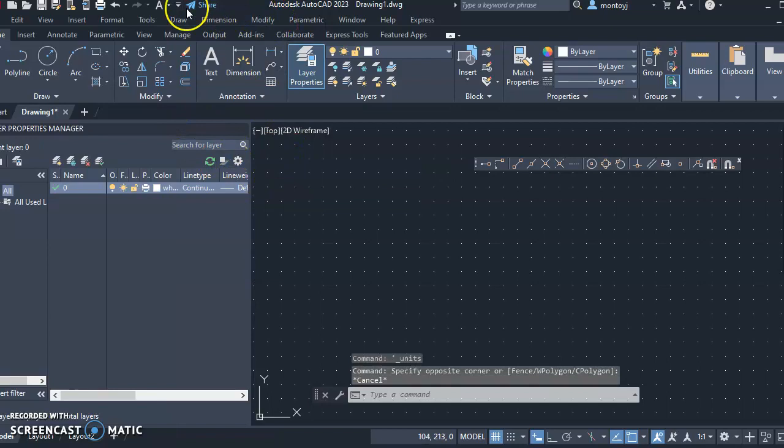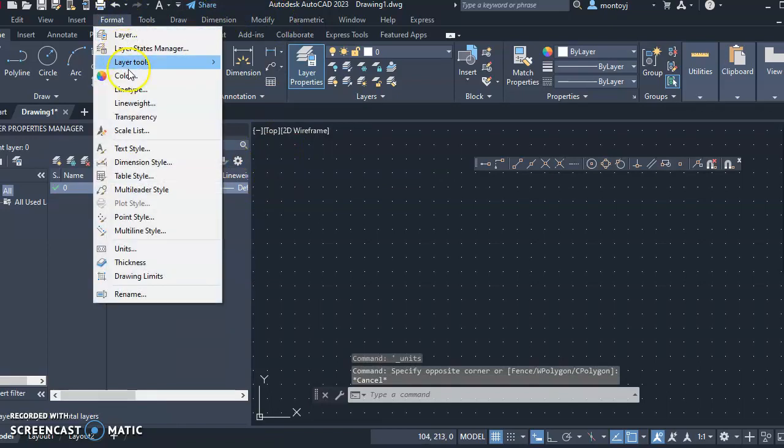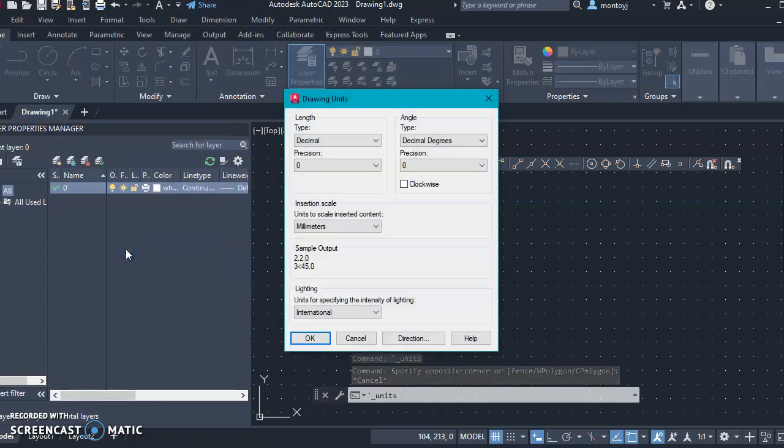Stop. Sticky buttons. Okay. Format, Units. What can we see here? We can see that we have choices: architectural, decimal, engineering, fractional, scientific. You could even work on your astronomy projects. You can do scientific, parsecs. But for us, we normally reside in the architectural. This particular project, our first, is decimal. So let's stick with that. Millimeters are used.